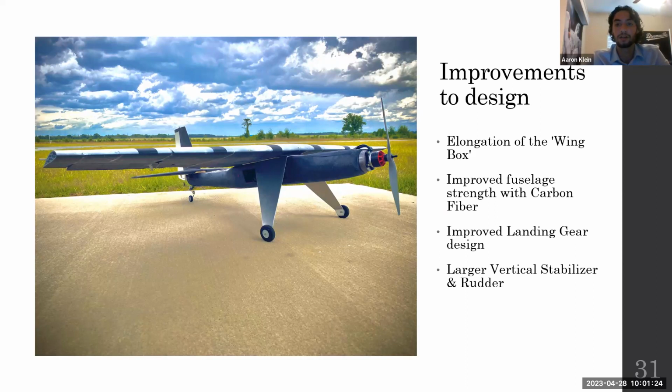The new landing gear design also had the front wheels placed further in front of the center of gravity. With our plane having a heavy ballast in the nose, this lessened the chance that the plane would fall forward and give more clearance to the propeller.